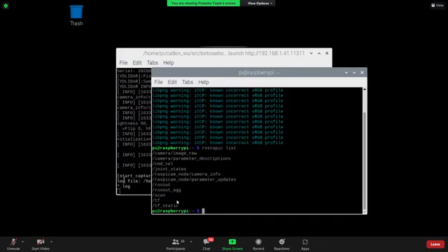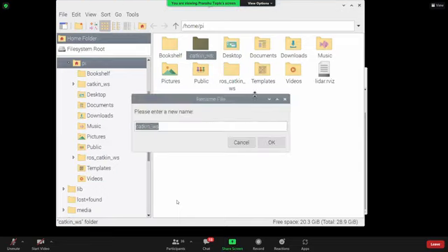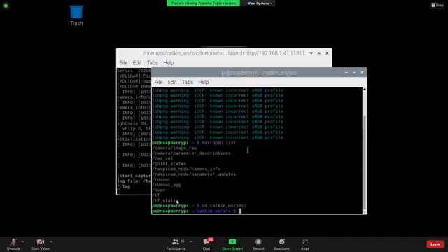So today what we will be doing is we will be trying to get camera used with OpenCV. So we will be creating a node. So for that, how to create a node? So let's consider I will make a package right now. So I will go to my source file, which is cd catkin workspace src. And now today I will be creating a package which is like catkin underscore create underscore pkg, which is catkin create package, the name of my package, whatever I want. So I will say ball follower,